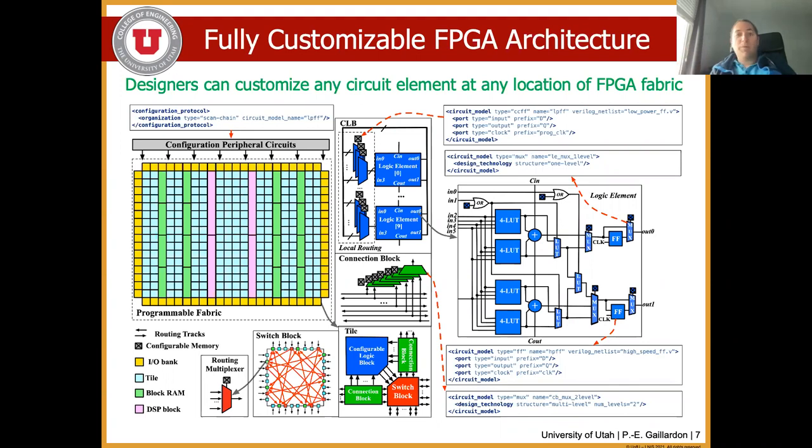With our framework, you are able to say, I want to use this type of MUX. I want to use this type of buffers here and there, because you control the FPGA architecture. So it's simply a way to replace the tedious manual efforts of making full custom layouts and definitions yourself. The tool does that for you, but you still need to provide all those low-level details.